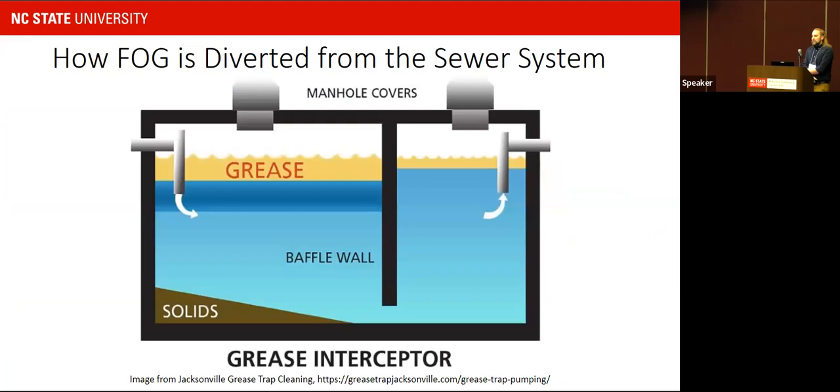That expense prompted us to develop a strategy to keep FOG out of the sewer. And that is to require actors that produce lots of FOG, like food service, to install grease interceptors. The grease interceptor works by taking advantage of grease's tendency to float to the surface of a liquid. Everyone knows this from cooking. When you boil pasta, you see the oil rise to the top.